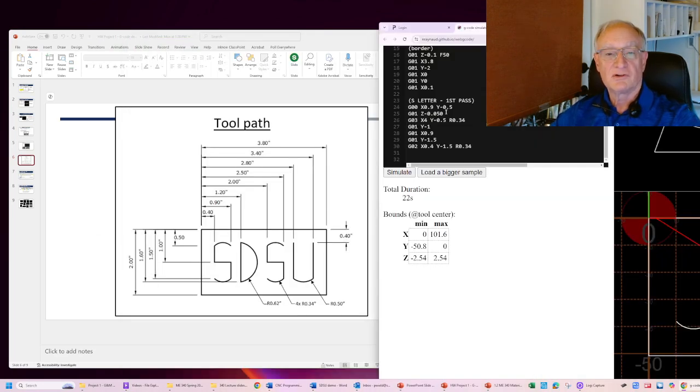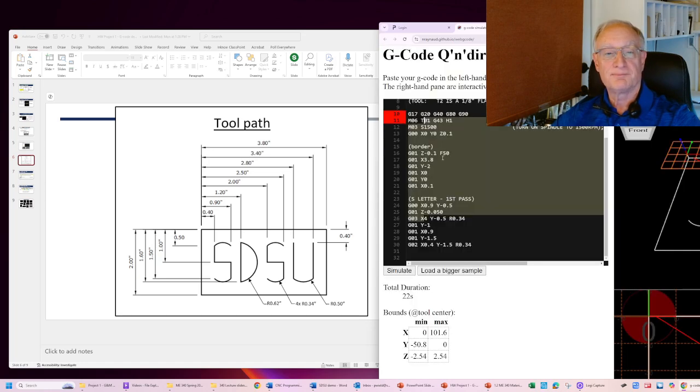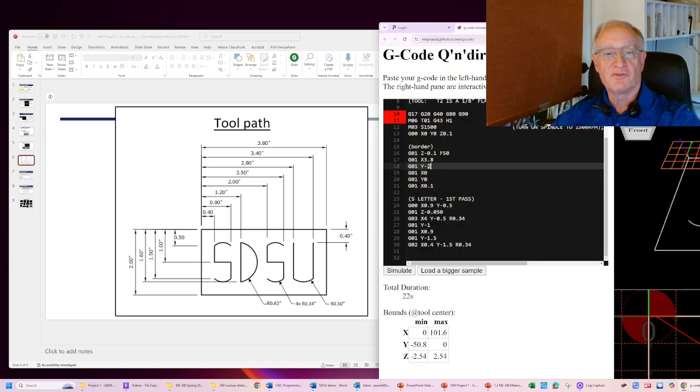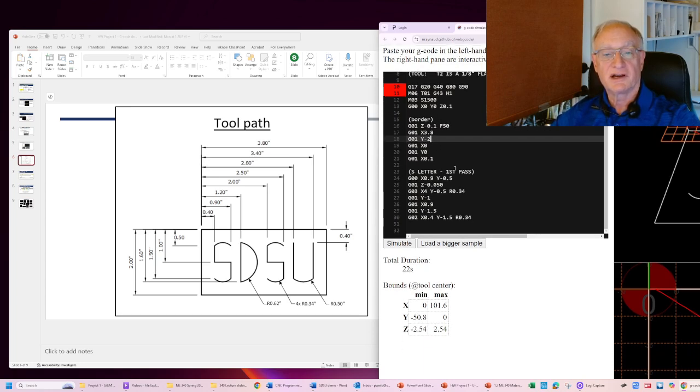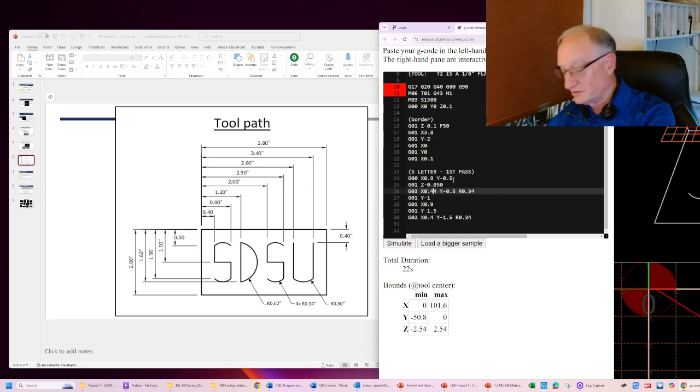That's the absolute value at depth of 50 thousandths. Then I'm making a counterclockwise arc, but I typed in a 4. Maybe you've noticed that before I did, and you were saying, Professor Wheel, you got an error here, you got to fix it. We'll fix it now.